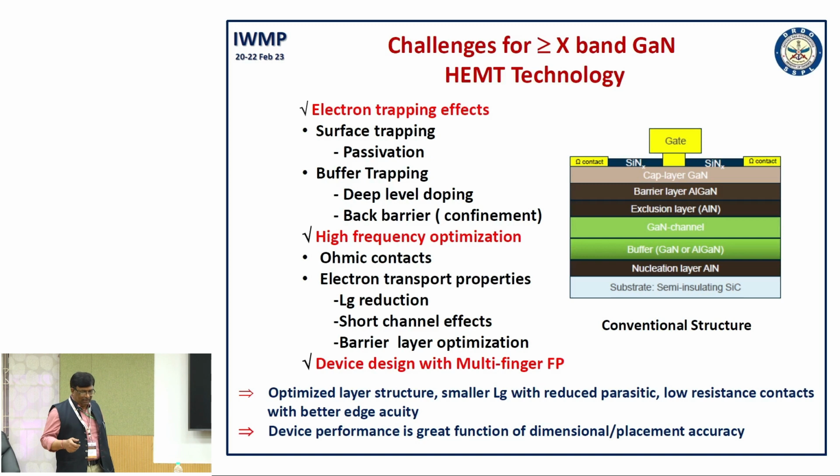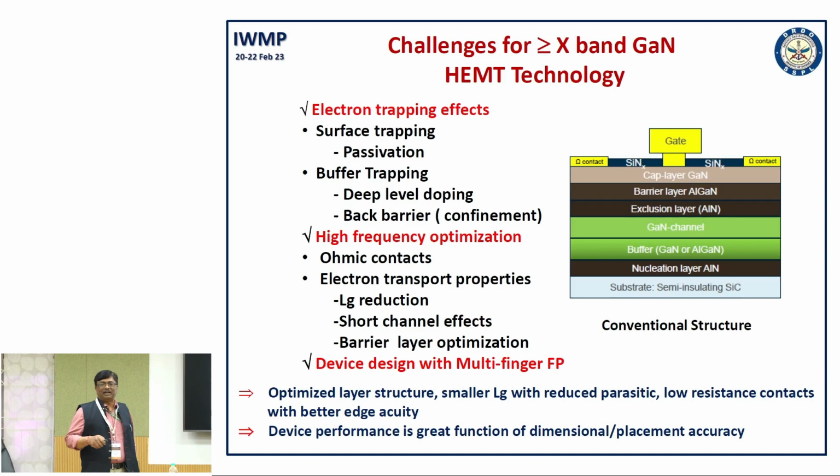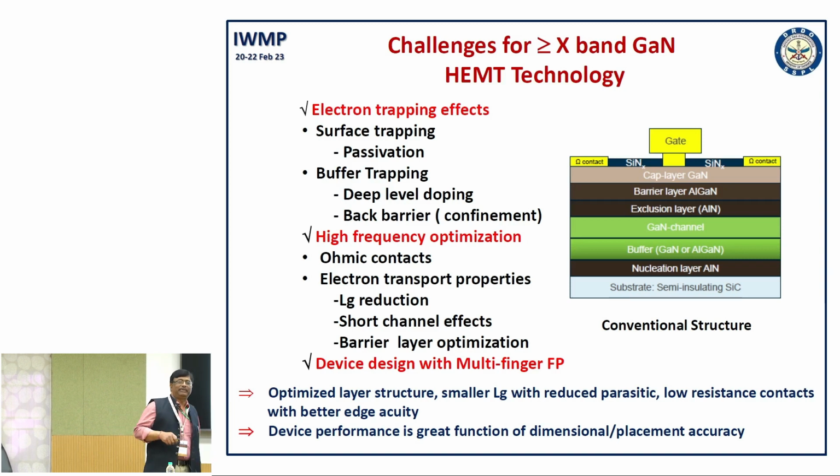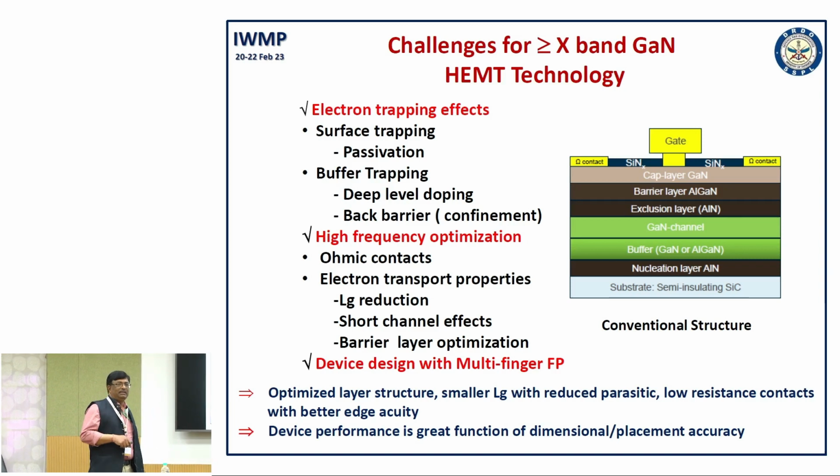And since we are going for gallium nitride technology, because we can extract high power by applying higher voltages because of high band gap, to have very high operating voltage, your gate drain breakdown voltage must be very high, but that is a function of electric field between gate and drain. So, we need to reduce the electric field peak between gate and drain. That reduction in peak results in higher breakdown voltages.